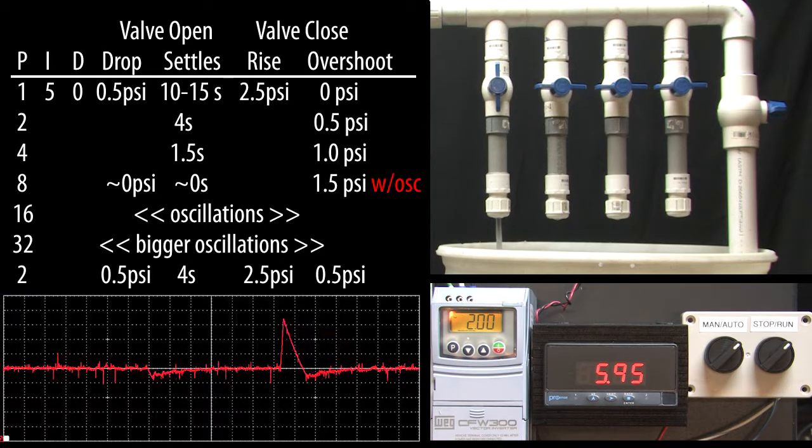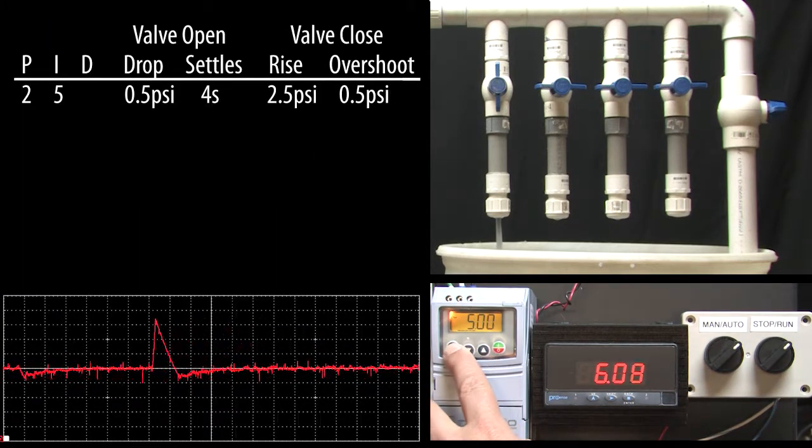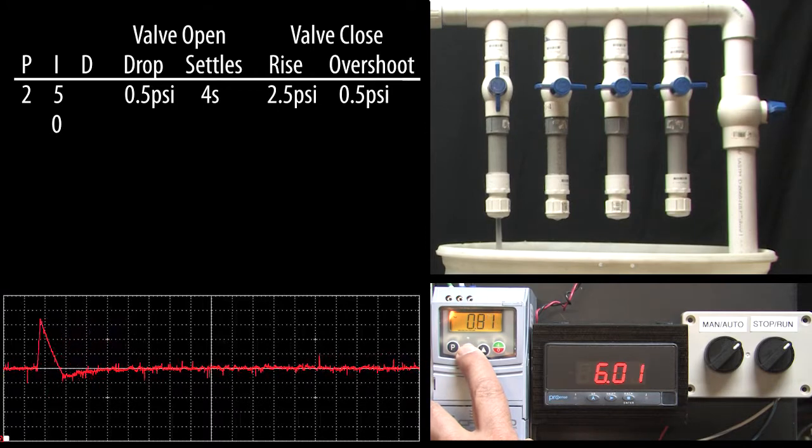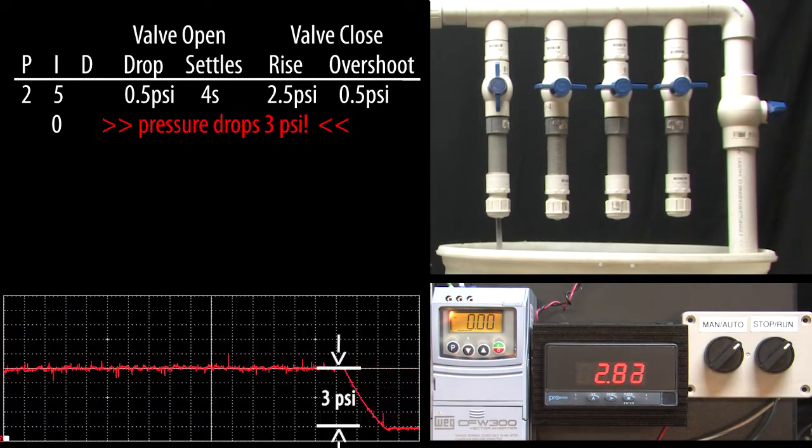Okay, that gives us a good feel for how P affects things. How does the I term affect things? Well, let's go to parameter 932 and find out. The default I is 5. Let's turn it off by entering a 0. Uh-oh, what happened? Our pressure dropped by over 3 psi.